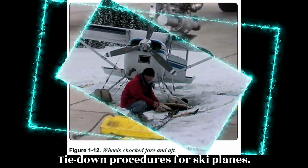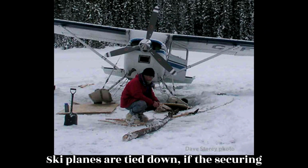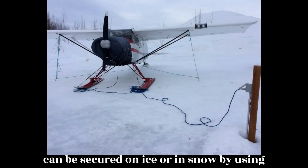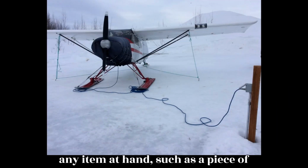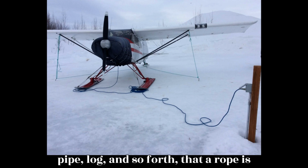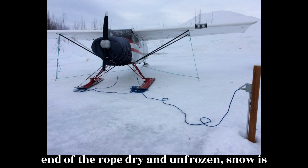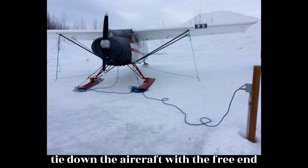Tie-down procedures for ski planes. Ski planes are tied down, if the securing means are available, in the same manner as land planes. Ski-equipped airplanes can be secured on ice or in snow by using a device called a deadman. A deadman is any item at hand, such as a piece of pipe, log, and so forth, that a rope is attached to and buried in a snow or ice trench. Using caution to keep the free end of the rope dry and unfrozen, snow is packed in the trench. If available, pour water into the trench. When it is frozen, tie down the aircraft with the free end of the rope.